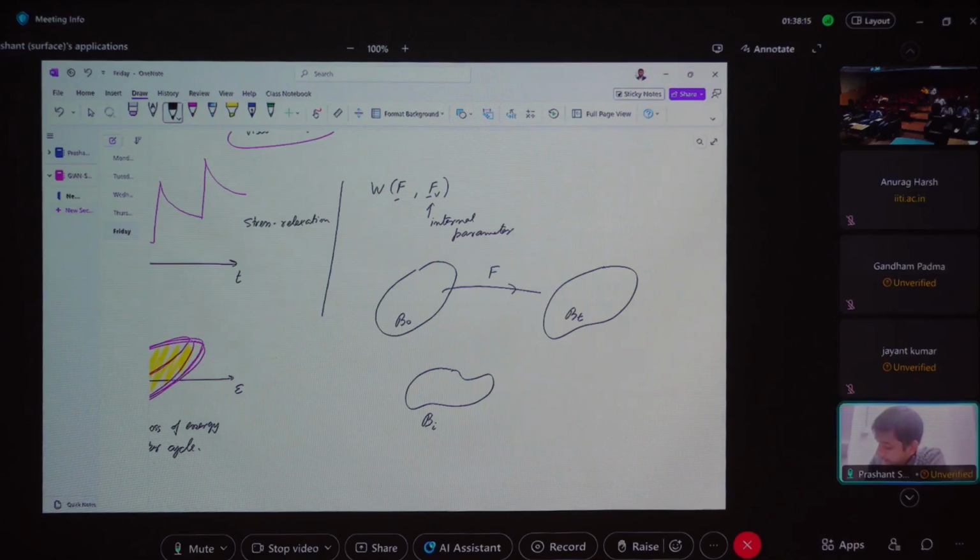And what basically Pi is, it's linked to the reference configuration by a purely viscous dissipative motion, and from here to there it is a purely elastic deformation. So F is Fe Fv because of that relationship.